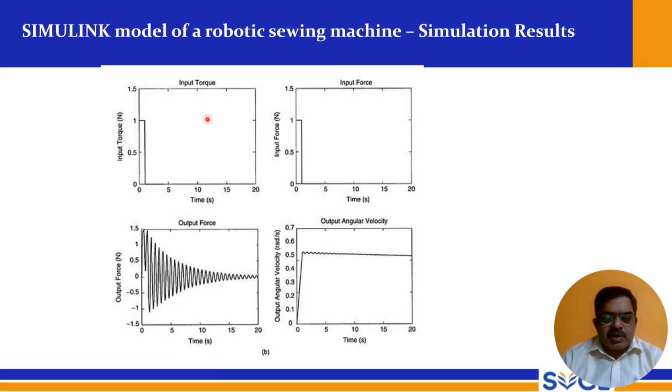So the input torque, input force, output force, and output angular velocity graphs can be obtained directly in Simulink, and those can be recorded or downloaded. And if you see MATLAB,